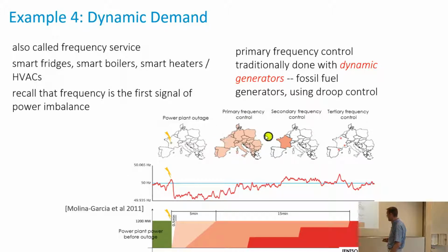The secondary reserve is across the entire interconnection. The primary frequency response which occurs here is across the entire interconnection. So when one nuclear plant has a failure in France, all generators in Poland react by generating more, and all over Europe. And because we have a huge system, the inertia of such a system is large, and that makes it stable. Does not exclude catastrophic failures either, but it makes it very stable.